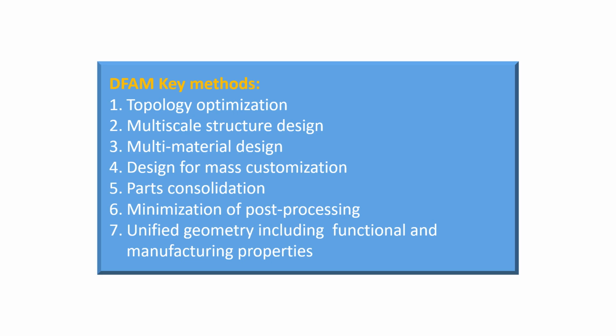2. Multi-level structural design and lattice structures. Thanks to the properties of AM processes, geometrically complex parts can be implemented. This gives designers a great deal of design freedom to use cellular structures or lattice structures as both a very small structure and a normal-sized structure to achieve advantageous properties. Lattice structures implemented in different size classes can be used effectively to reduce weight.